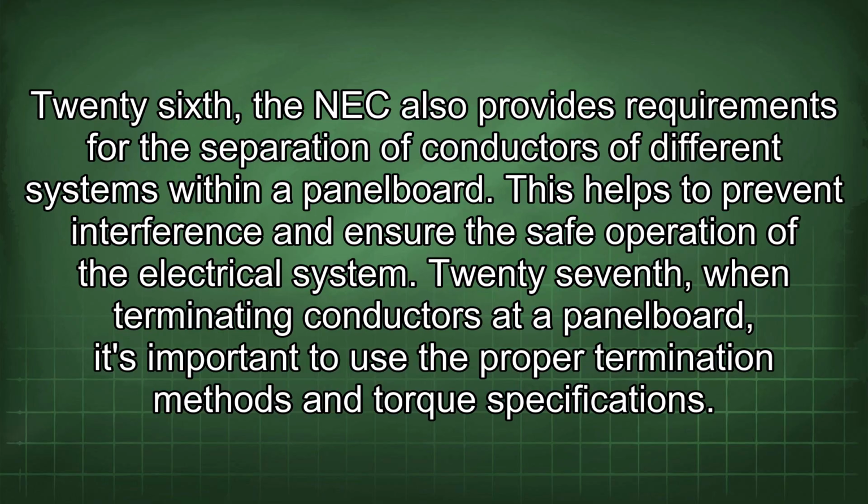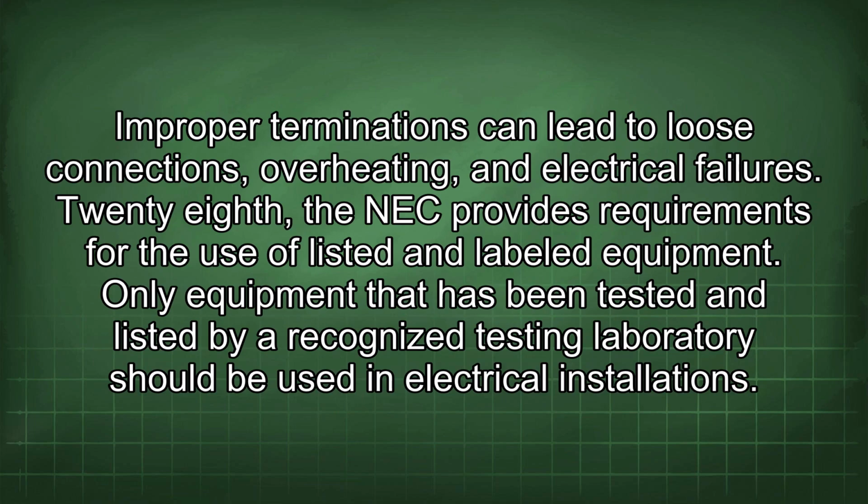27th, when terminating conductors at a panel board, it's important to use the proper termination methods and torque specifications. Improper terminations can lead to loose connections, overheating, and electrical failures.